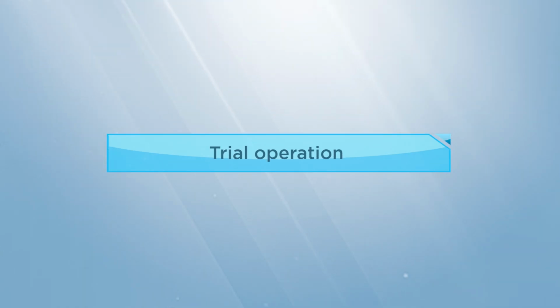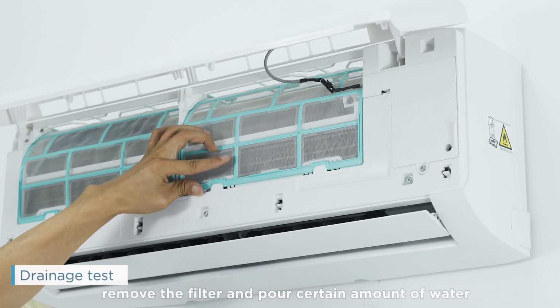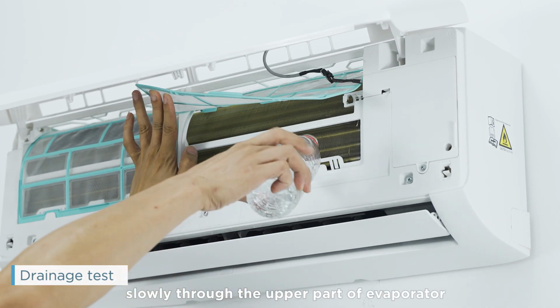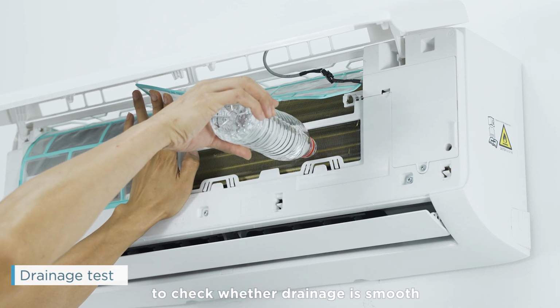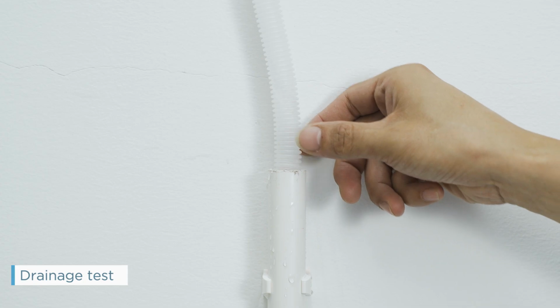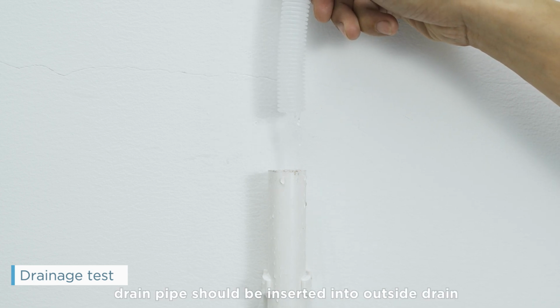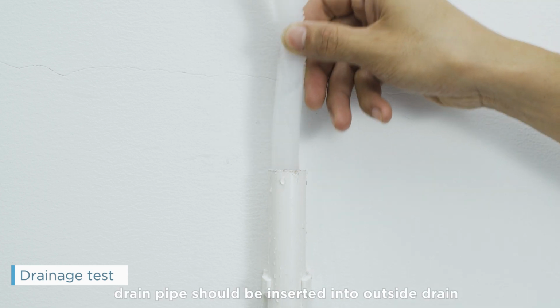Trial operation. Open the panel, remove the filter, and pour a certain amount of water slowly through the upper part of the evaporator to check whether drainage is smooth. After it is ensured that water flows through the drain pipe smoothly, the drain pipe should be inserted into the outside drain pipeline.